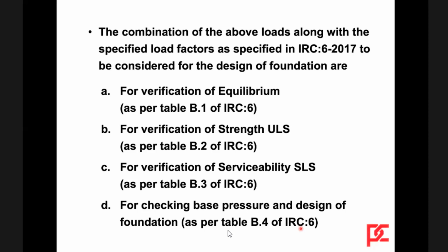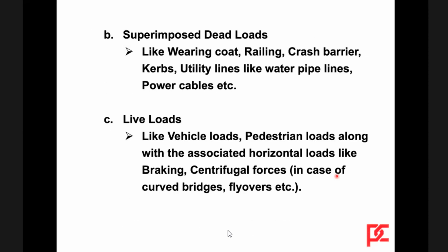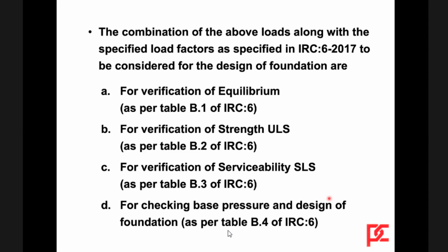The combinations of the above loads along with the load factors as specified in IRC 6 to be considered for the design of foundations are: for the verification of equilibrium, the loads and the load factors are given in Table B1. For the verification of strength in ULS, Table B2. Verification of SLS serviceability, B3. Checking of base pressure and design of foundations, this is Table B4.